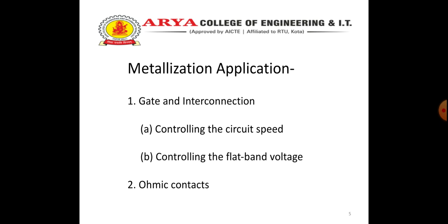Now, ohmic contacts. A good ohmic contact, usually formed by depositing a metal on the semiconductor, does not disturb the device characteristic and is stable both electrically and mechanically. It has a resistance called contact resistance that should be negligible compared to device resistance.